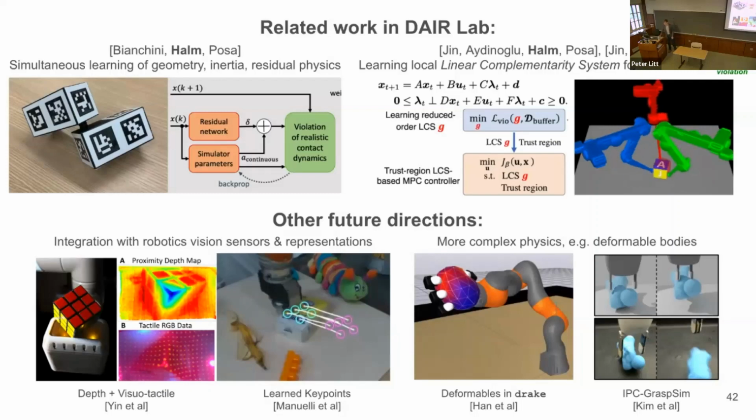even motion that isn't chaotic can have these near discontinuities and have these numerical difficulties in the model identification process and in control. Every walking robot is going to make footsteps at the end of the day, for one. And so I think models like this can provide a perspective on what actions are not only good, but are reliable, to give a computational framework that pairs with that intuition.